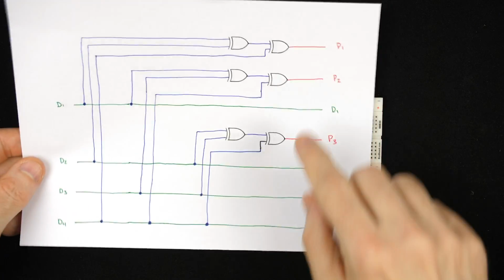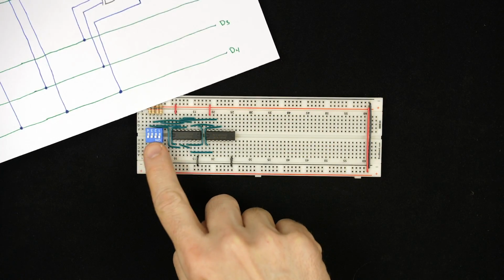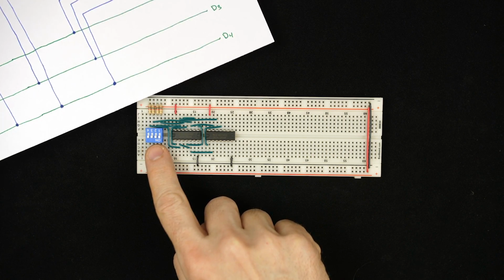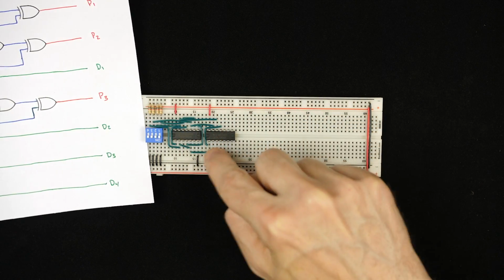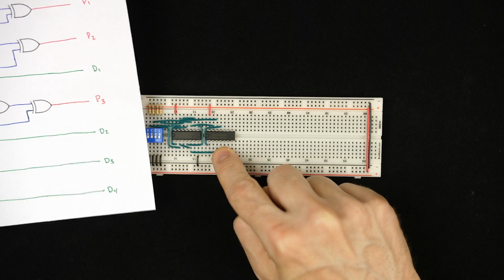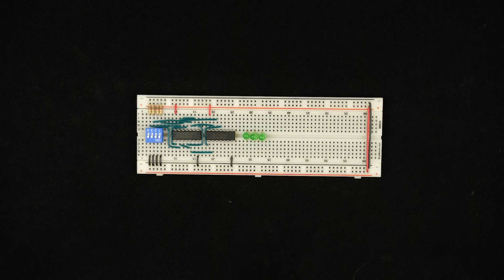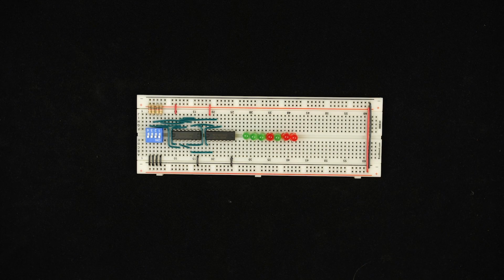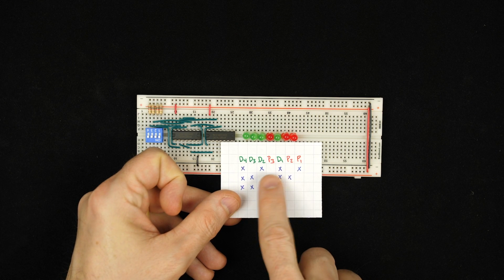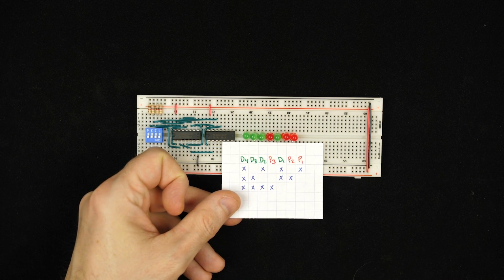Okay, and that's it. So we've actually got all of these XOR gates hooked up, and we've got our inputs over here on the switches. So somewhere in here, we've got our four data inputs, as well as our 3 parity bits in a couple different places coming off these chips. So now what I'll do is hook up some LEDs so we can actually see what all 7 of these bits look like a little bit easier. So this will be the 4 data bits as well as the 3 parity bits in the same configuration here, so we can easily see what's going on.